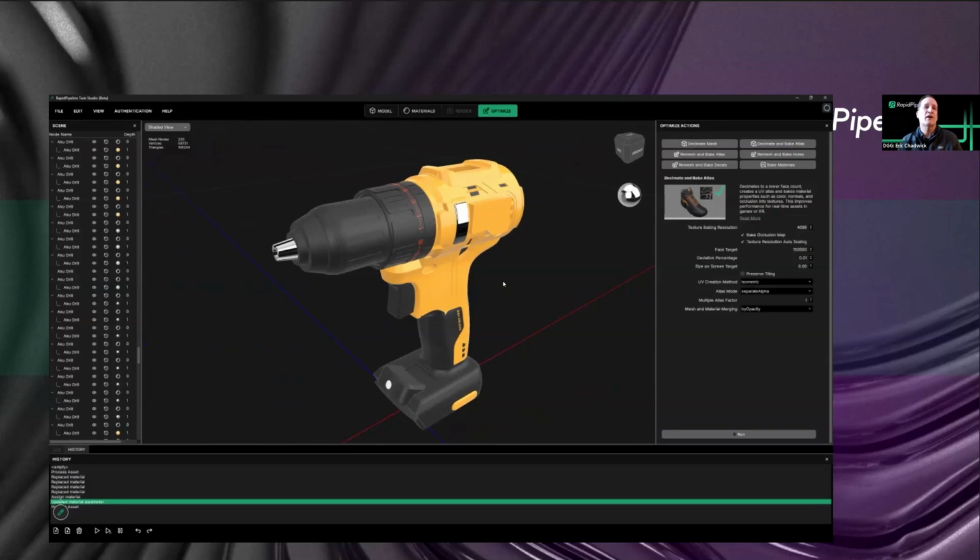By opacity is cool. If I have materials with transparency, say a car with glass windows, or say a tea kettle that has glass parts in it, typically you want those glass parts to be kept as separate nodes so that when it renders those in a real-time renderer, it sorts them correctly. That's what this does. This will basically collapse all the opaque parts down into one node because they don't need sorting.